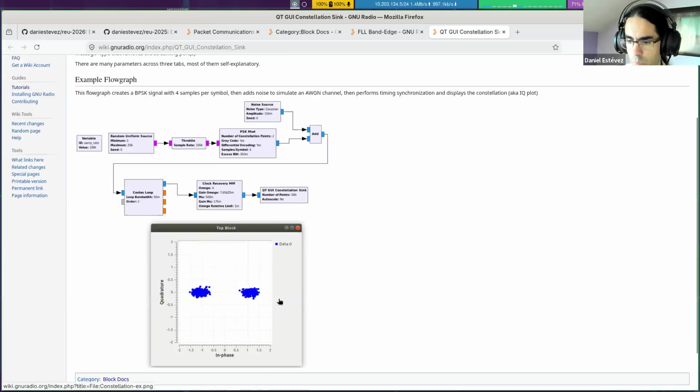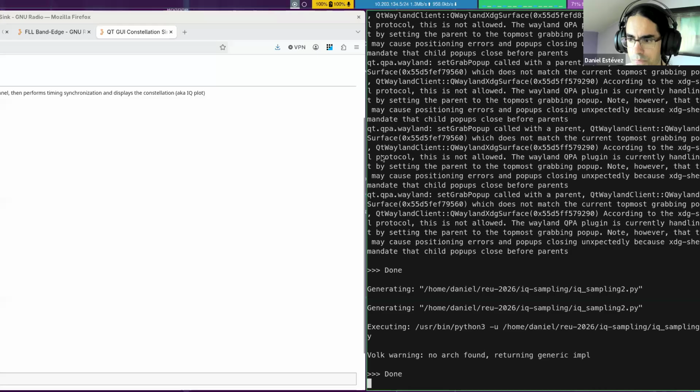And there is an example. And this is a digital communication signal. So you can see there are points here, there are points here. This is the way that a binary 0 is sent by the transmitter. This is the way that the binary 1 is sent by the transmitter. So this is a very simple encoding. You could imagine that another radio modulation could have more points wherever you want to put them, and they would encode more complex values, essentially multiple bits per point I have on the constellation diagram.